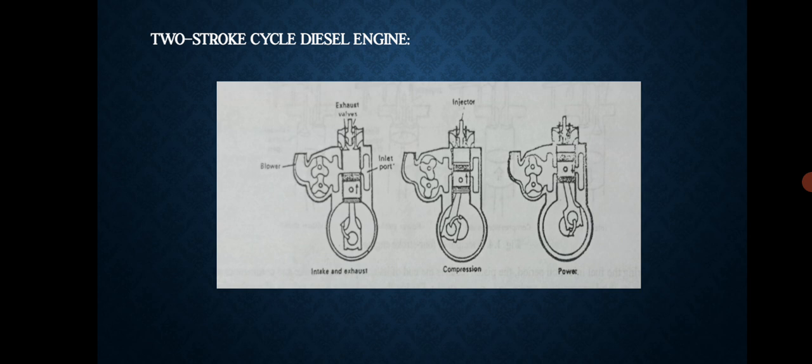The compression pressure is usually very low, being just sufficient to enable the air to flow into the cylinder through the transfer port. When the piston reaches nearer the bottom of its downstroke, the air thus flows into the cylinder where it is compressed by the piston as it ascends until the piston is nearly at the top of its stroke.